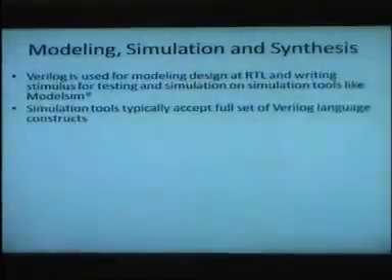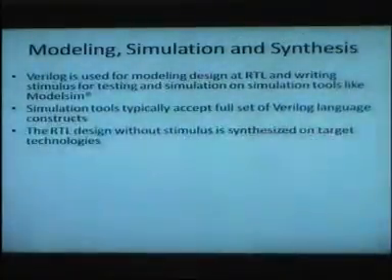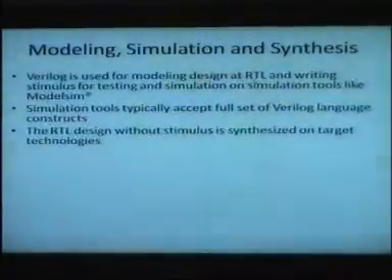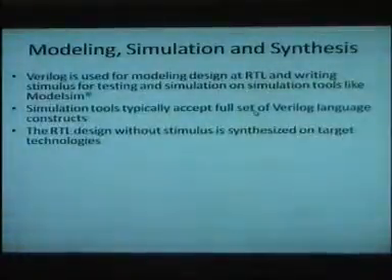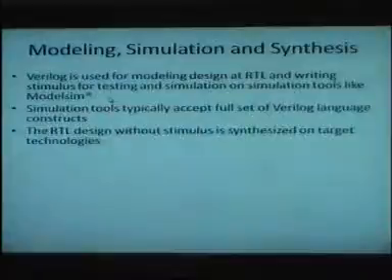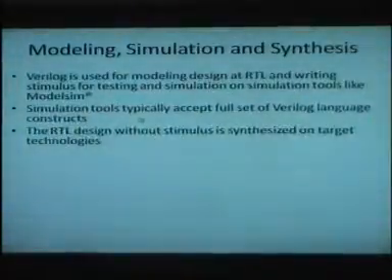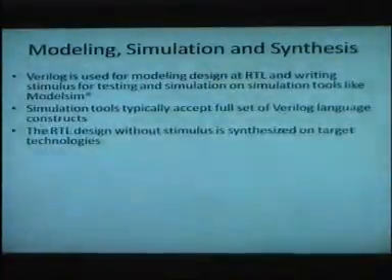So Verilog gives you provisions to write the design at RTL level, write the stimulus, write the test vectors, and use a simulator, which usually we use ModelSim. So that is what we'll teach you. Simulation tools typically accept the full set of Verilog language constructs. Verilog is a rich language.